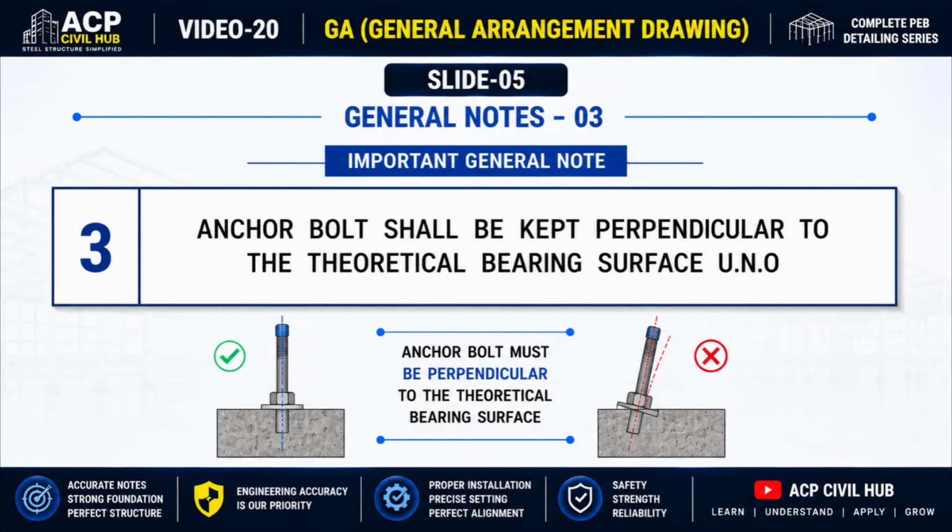Why is this important? When the anchor bolt is vertical, the base plate fits properly, the nuts and washers sit evenly, and the column transfers its load safely to the concrete foundation. However, if the anchor bolt is tilted or out of alignment, problems can occur during steel erection.